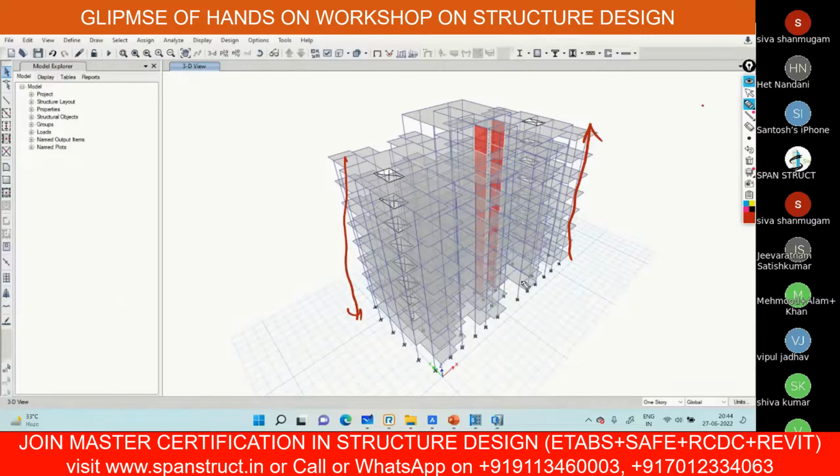So this matters when you want more accurate results, when you're doing some typical analysis, like deep beam analysis and spandrels. In that case, the construction sequence analysis will give you a real result. Because when you're doing the analysis, we give the load from top to bottom, but actually construction starts from bottom to top, so the result may vary. When you want to make the result accurate, you have to perform the construction sequence analysis.